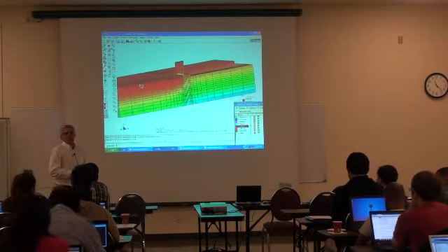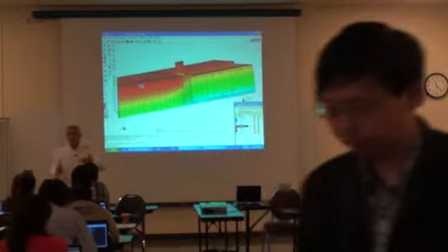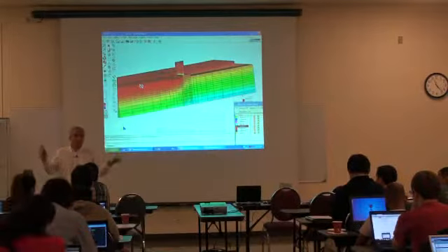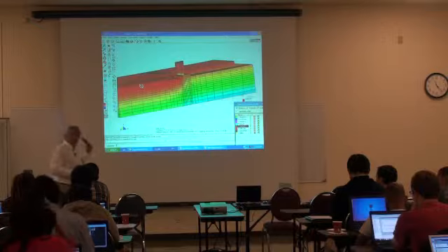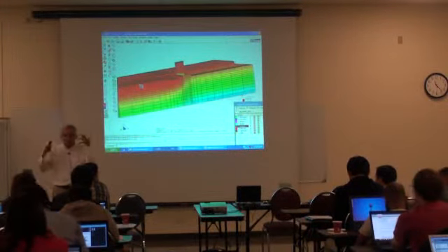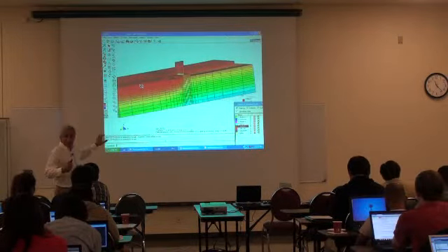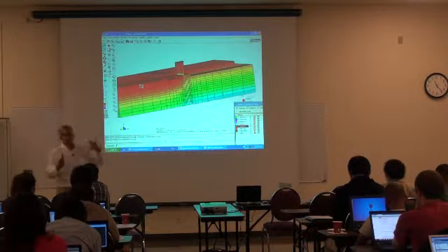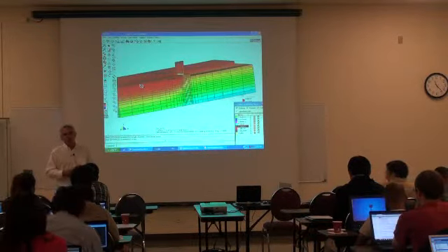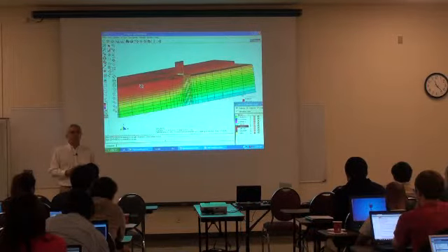What you should use there is a pressure dependent multi-yield, the O2 or the original one, but you have to use the quad UP. Now, if you're going to use a multi-phase element, use either the stabilized single point UP or the 9-4 UP. I would not suggest using the quad UP element because it's not stable.